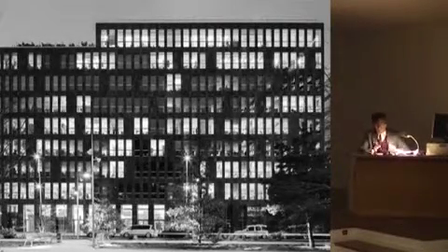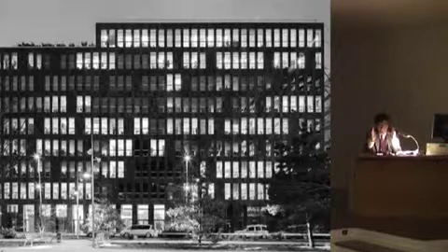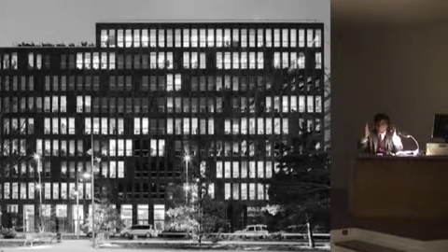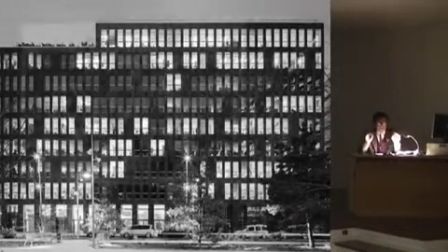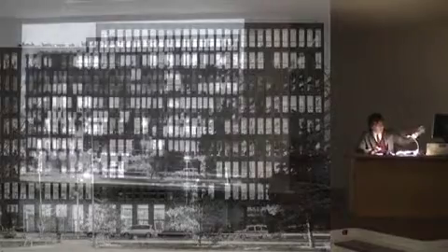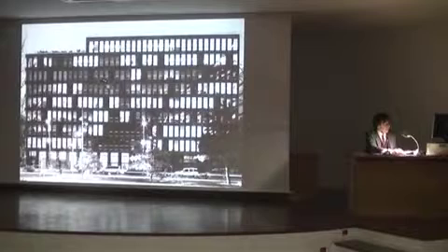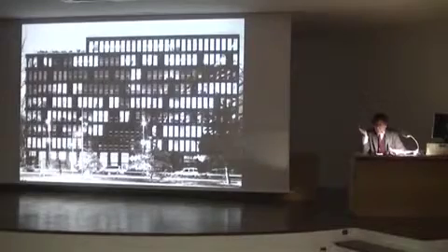There are some cases like this building. What we did with Alberto, in this case in Paris, was provide metal frameworks, aluminum in this case. You prepare the carpentry, and it comes with an aluminum framework that takes the thickness of the insulation chamber wall and protrudes outside just enough to receive the stone facing, so it's impeccably sealed. You can see that here. And the fact that several windows like these don't exist, we reached that conclusion because of the French regulations.